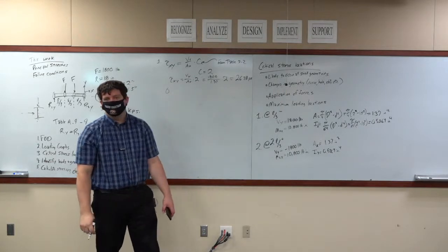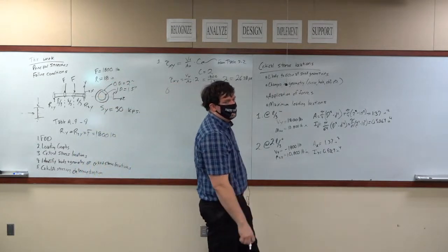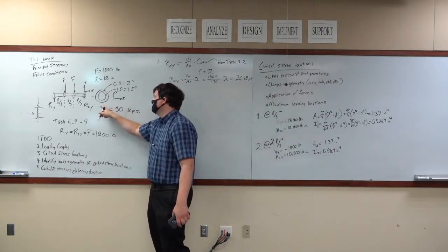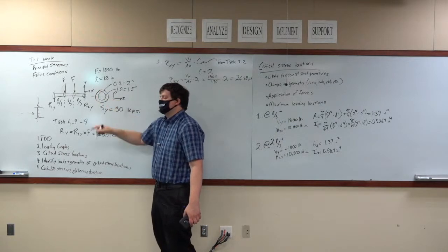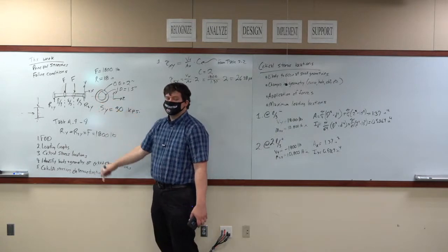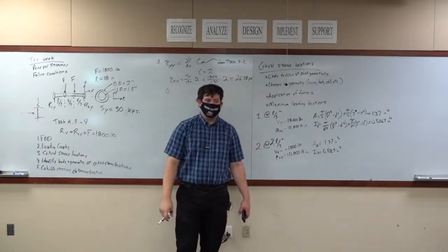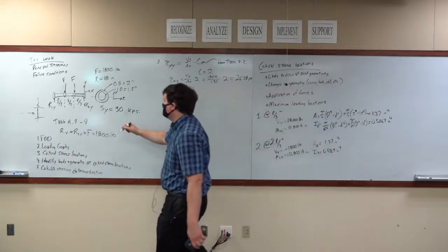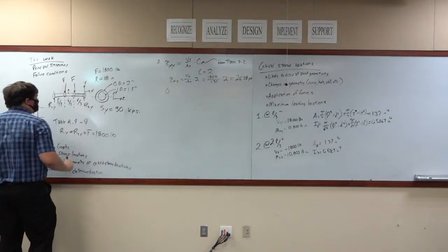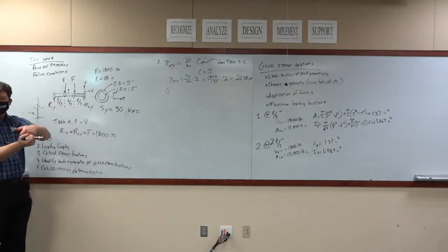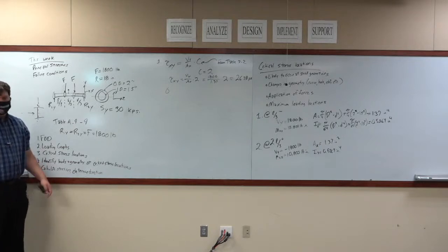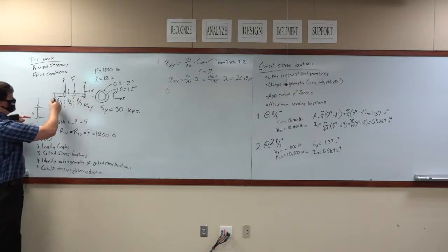What direction is the normal stress in? If we cut that cross section out, what force is required to maintain tension or compression in this element? What direction does that have to be in? If it's in the y direction, it means it's being exerted this way. That means it is stretching or compressing in that direction. Is that correct? Well, not really, because that's not going to create tension on the top, compression on the bottom.